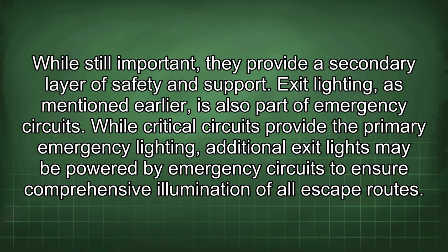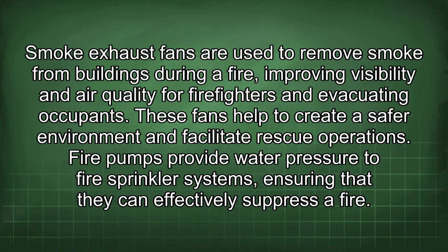Exit lighting, as mentioned earlier, is also part of emergency circuits. While critical circuits provide the primary emergency lighting, additional exit lights may be powered by emergency circuits to ensure comprehensive illumination of all escape routes. Smoke exhaust fans are used to remove smoke from buildings during a fire, improving visibility and air quality for firefighters and evacuating occupants. These fans help to create a safer environment and facilitate rescue operations.